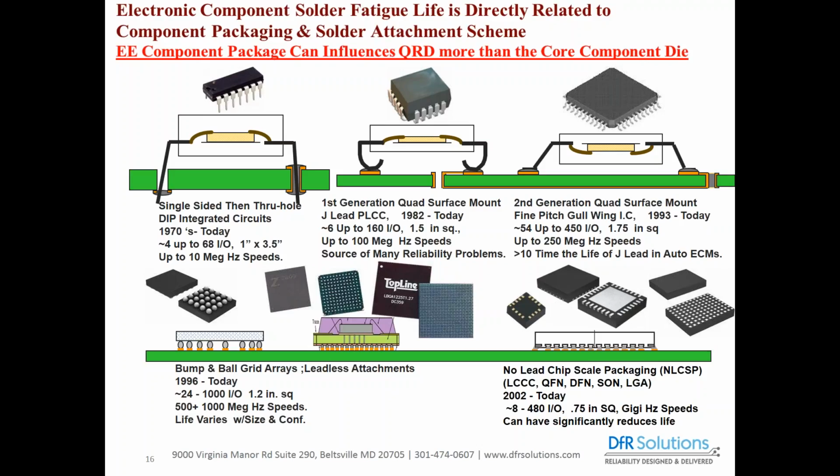They didn't care why it failed, they just cared that, oh, that part failed, so we're going to give it a black mark. Well, they didn't account for the fact that components were failing because they had weak attachment systems, weak solder joints. And when we produced the stronger solder joints, our reliability greatly improved and our durability was greatly extended.